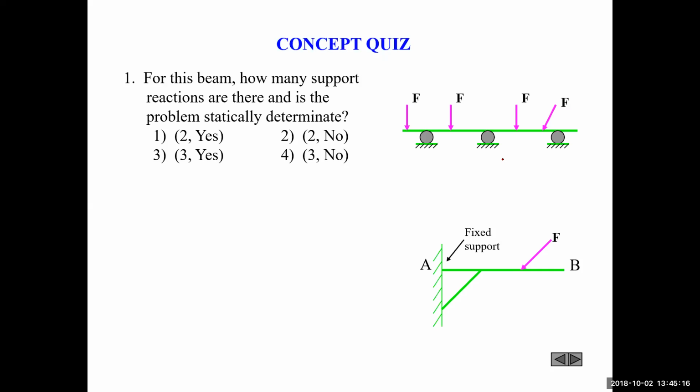So you can pretty much guess that there's going to be 3 support reactions. Is it considered statically determinate, though? That means, can you find out what those forces are? And is it actually stable? If those are rollers, is it stable? No, it's going to just roll right off, right?